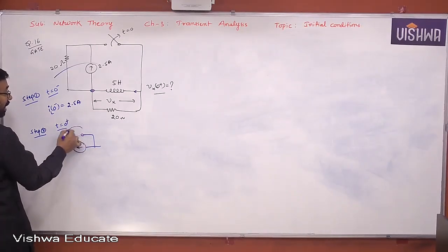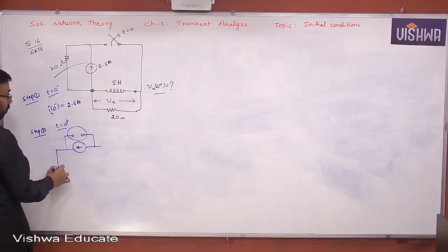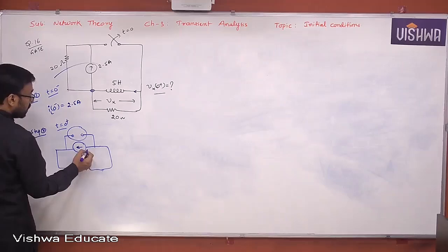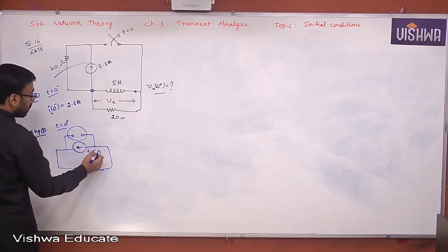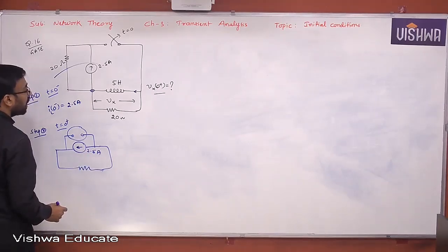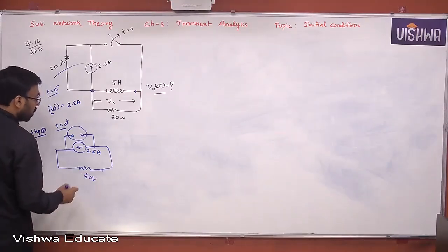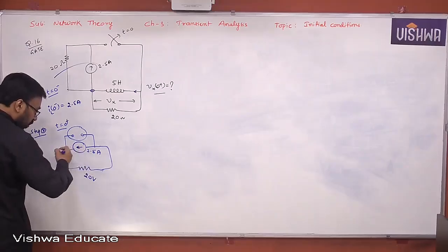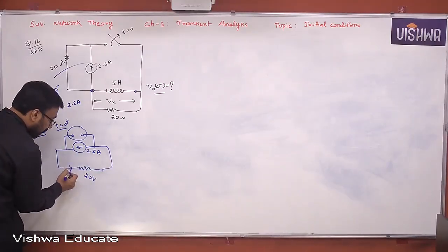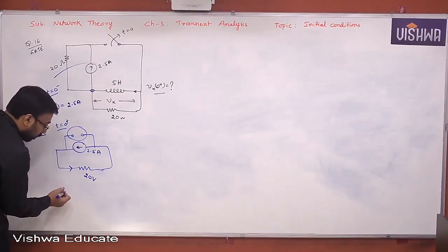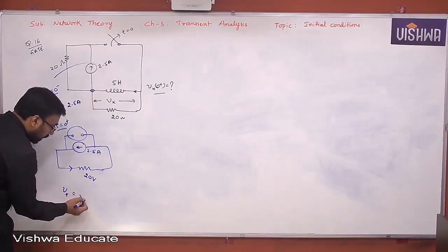Okay. With a parallel inductor model. And you got the resistor as it is. And this is 2.5 ampere. This is 2.5 ampere. And now this is 20 volt. Yes or no, all of you? So what do you get here? The current flowing in this element is what? Actually in this direction. How much current is flowing? This is 2.5. Then finally Vx value is 20 into 2.5.